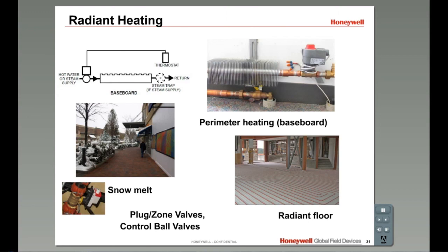In certain locations, radiant cooling may also be used, but it is critical that the surface, the floor perhaps, does not cool below the dew point and become wet and slippery. These applications may use ball valves, cartridge cage valves, and globe valves, or plug-style valves. The valves may have two-position actuators with or without spring return, although modulating actuators are also used.